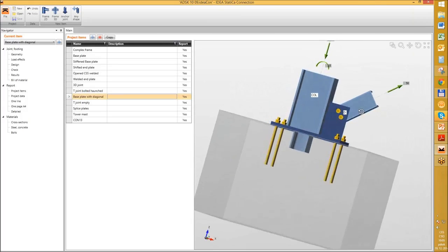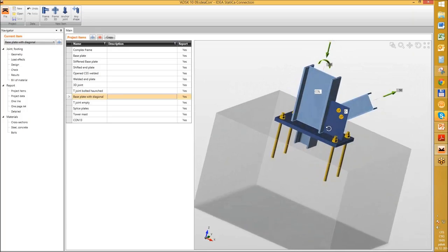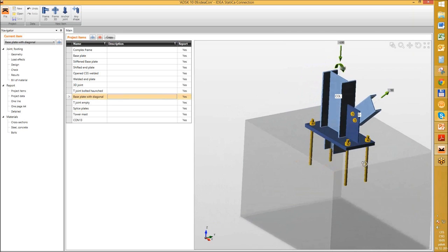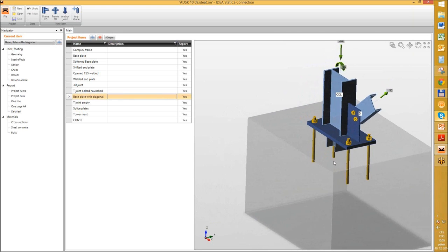It is quite important because if you calculate it like that, the situation can be worse, but it can be also better. For instance, here this gusset plate in fact works like a stiffener of the base plate. So if we connect this one more member to the connection, in fact we can help the connection, and we can make the more efficient design.